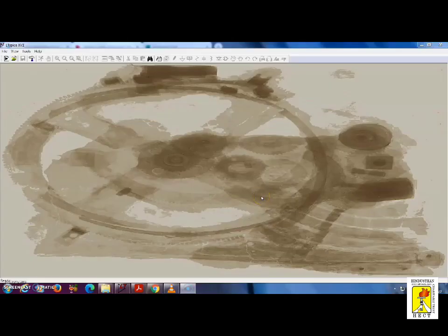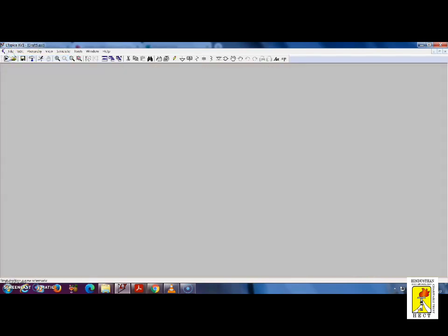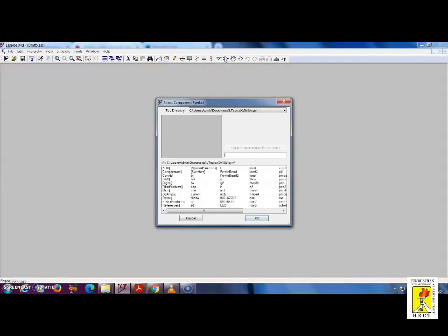Welcome. In this video we are going to look at how to do the analysis of a junction field effect transistor, how to measure the transfer characteristics and drain characteristics using simulation using LTSPICE. Open LTSPICE, go to the File window, go to New Schematic and select the component.